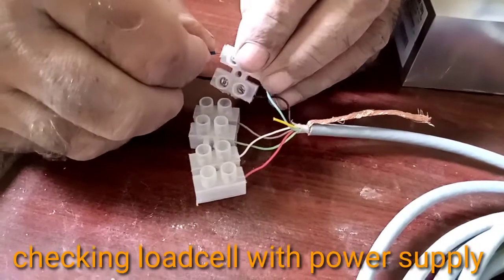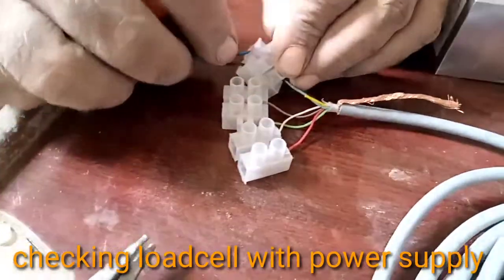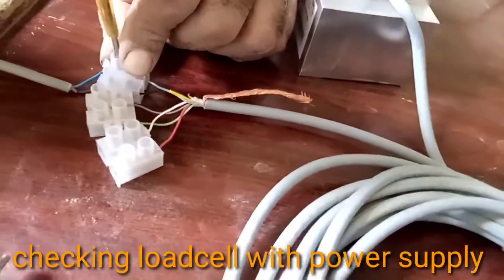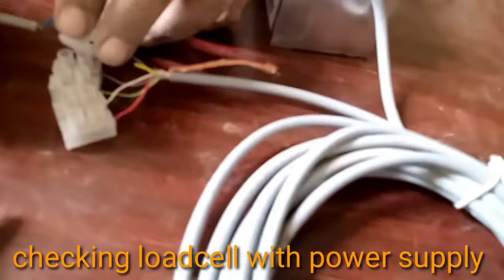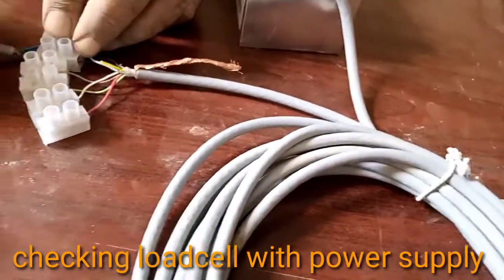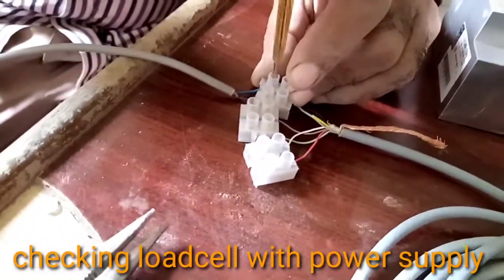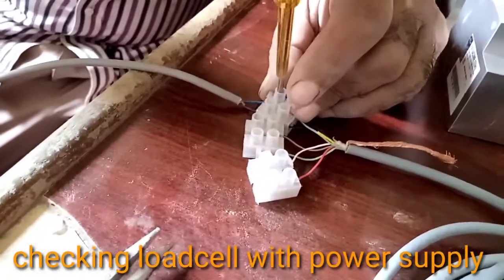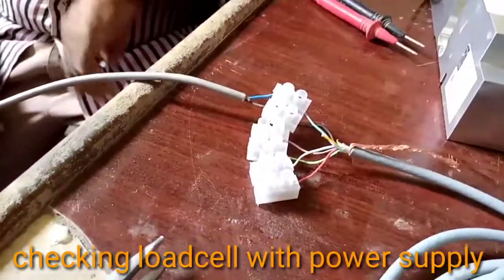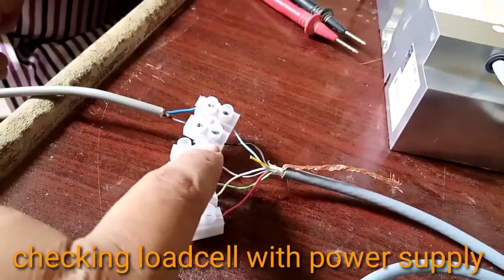You can connect it properly. For safety purposes, we connect all cables with PVC connectors and avoid a short circuit. When you install it on a controller, you must connect its ground wire to ground.